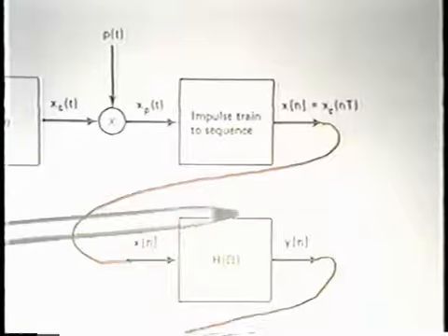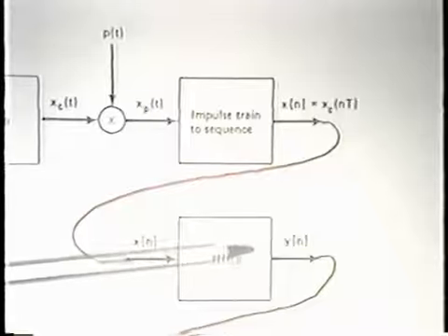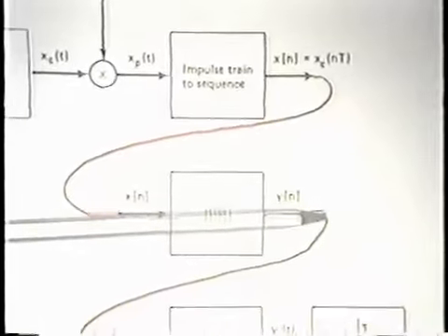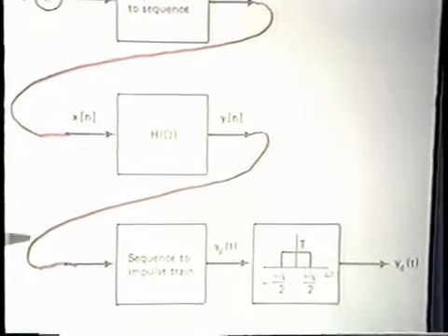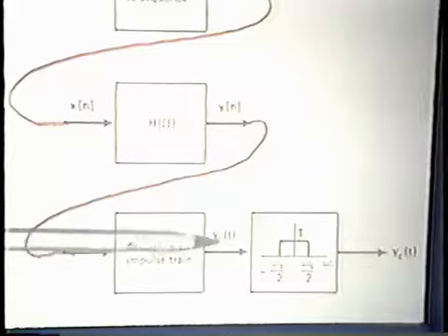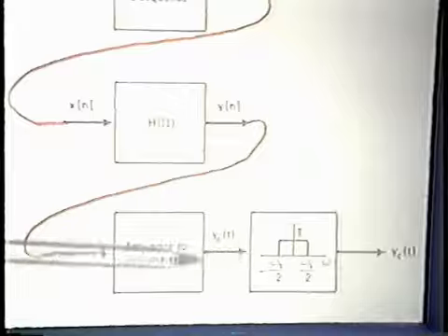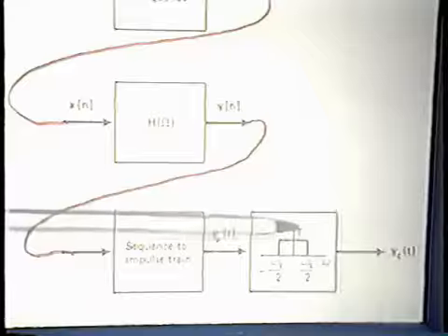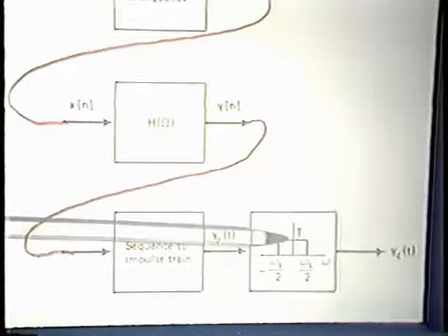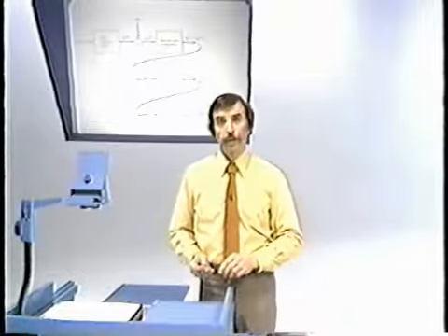That goes through the digital filter and gets attenuated or amplified appropriately. And then the output of that is converted back, and that's, again, a sinusoidal output. That gets converted back to a continuous time sinusoid, theoretically, as I indicate here, but again, as we just saw, really represented by a zero-order hold followed by a low-pass filter. So that's the overall operation, with one modification from the diagram that we have here.